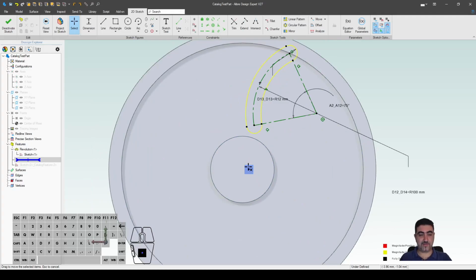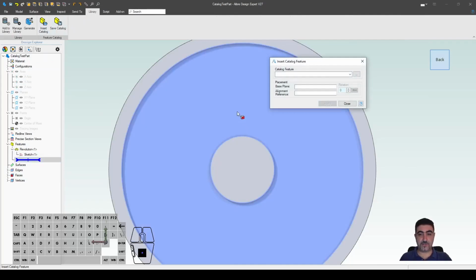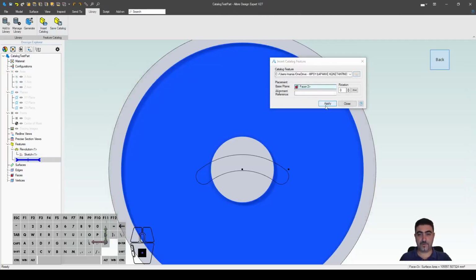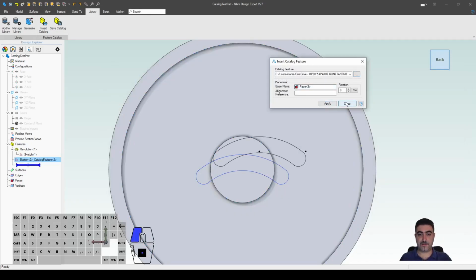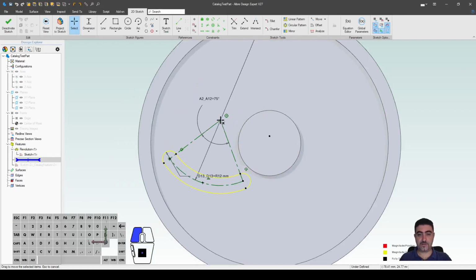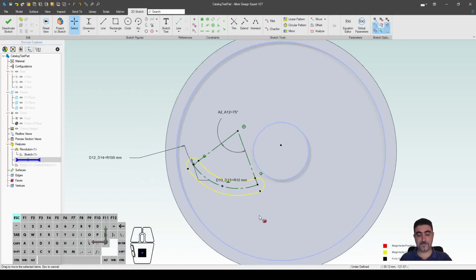And you can also see that the origin of this sketch was just thrown off by the alignment that I did. Okay. And to prove the point, if I delete it and bring it in again, it should be the curved slot. I want to put it on here, apply, okay. So you see now that the origin of the sketch, oh, it's still off. Okay. That is something that you really need to pay attention to, right?